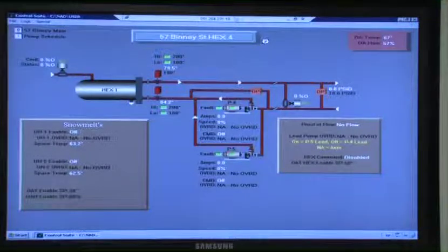You can also adjust the temperature that's going down the pipe, which is just about to the top right of the HEX1, right there is your set point, the black, 180. If you needed to, you can adjust that temperature as well. The glycol coming out temperature. Is that on a reset schedule? It's not on a reset, it's a fixed value, I believe. Which makes sense because it's all about heat. You don't want to reset it and never get the heat out there. You're basically trying to protect that space.